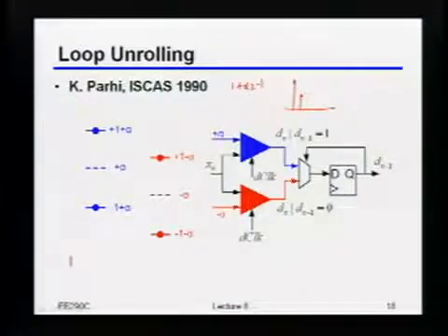Okay? So in other words, I can just have two different comparators with their thresholds shifted. And then in the digital domain, once I know what the previous bit actually was, select really what the right answer should be. In other words, which comparator I should actually be looking at. Okay? So just to clarify what these diagrams are showing you, this is just saying